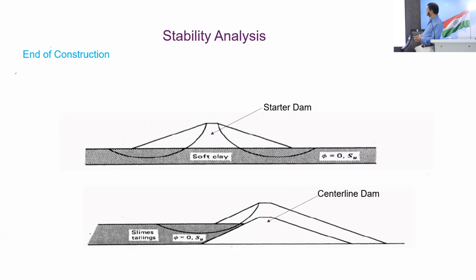So there you have to consider the undrained conditions. And the tailings are always undrained. So in the undrained condition, like I mentioned before, my target is this Su, shear strength undrained. This parameter is a very, very critical parameter for the tailings. And whatever you do, whichever method you follow, you should have knowledge about the undrained shear strength, which we will discuss more again.